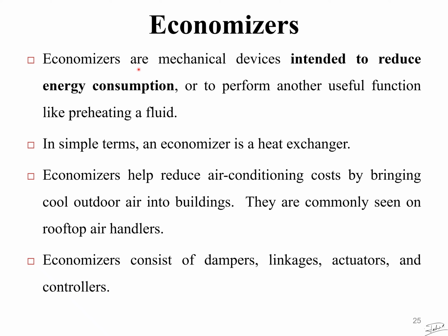Economizers are mechanical devices intended to reduce energy consumption or to perform another useful function like preheating a fluid. In simple terms, an economizer is a heat exchanger. Economizers help reduce air conditioning cost by bringing cool outdoor air into buildings. They are commonly seen on rooftop air handlers.